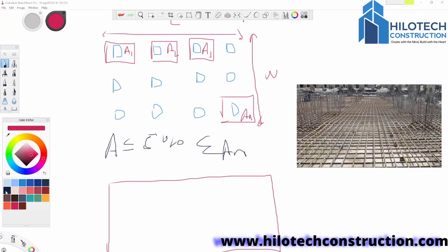Of course in here now you are going to have all your pillars exactly the way they were before. So that is A1, A2, A3, A4, and we continue until you have AN here. Of course the difference here is that instead of having individual footings, you have one footing. Why? Because it satisfies this condition.